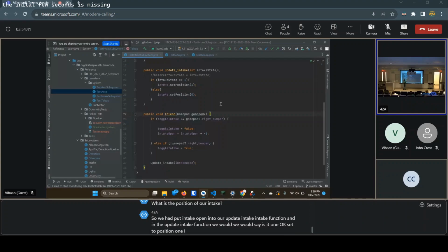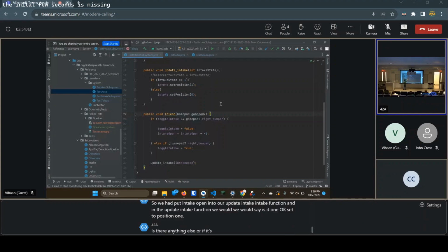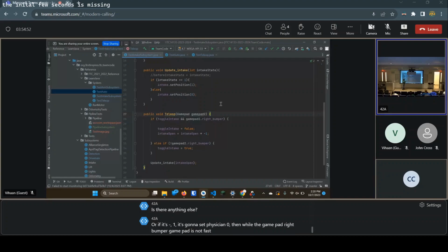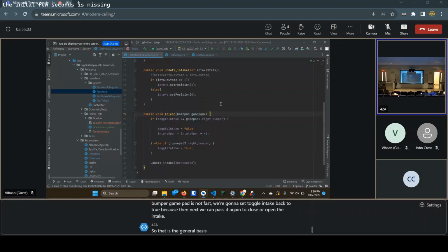This shows that this is a teleop file, saying that it's going to repeat again and again, and it's named test teleop, and it's an iterative op mode, another way of saying teleop. So on our driver hub, if we click the iterative op mode button, it's going to show a list, and in that list, there's going to be a file named test teleop, as we said @teleop there.